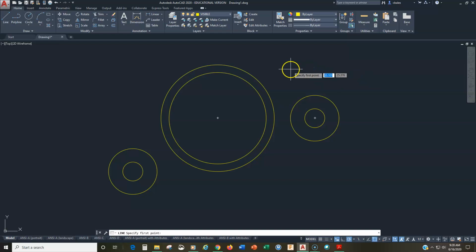So I'm going to type in TAN. Notice it goes right up to the dynamic input, and nothing else is on except the tangent. So I click on that. Now it turned off because it only lasts for 1 click. So now I have to do TAN again, like that. Let's do that one more time. Line, and then I type in TAN, hit the space bar, click right there, type in TAN, hit the space bar.